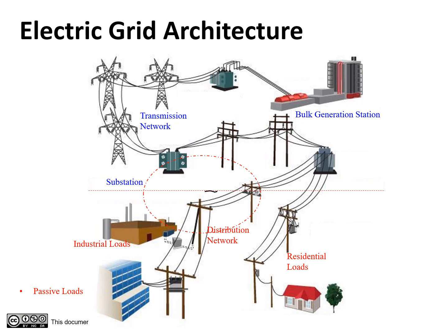Substations consist mainly of transformers to step up or step down the voltage level, switchgears, and protection devices. The end customers could be residential or industrial loads. In the conventional electric grid, loads are passive loads, which means they only consume energy, and the power flows in one direction from the transmission to distribution to loads. Protections and control systems are developed based on unidirectional power flow assumption.